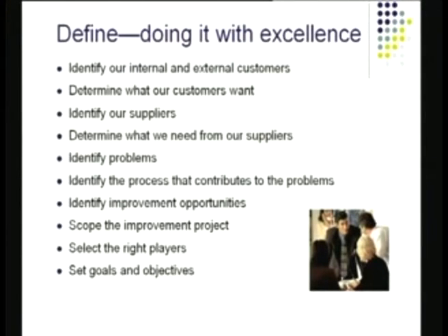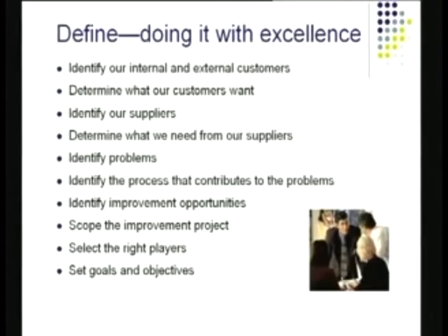Identify the process conditions that contribute to problems. This is like something, perhaps when humidity is high, temperature is high, speed is too high, or something like that, I have problems. Or when conditions are dusty, perhaps I have problems. Or when the worker is tired, I have problems. Or whatever it is. Or when the supplier is switched from A to B, I have problems, and so on and so forth. So this is something that I'll have to probably find out.